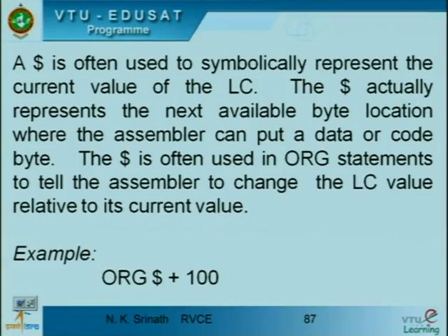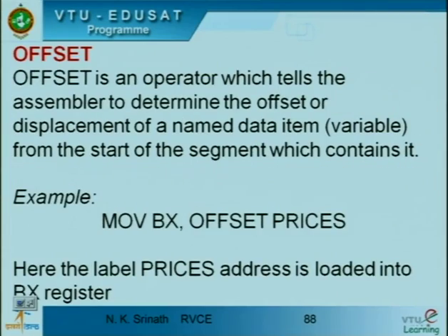It so happens that when you want some space to be left aside and the data to be stored later, you use this statement called ORG dollar plus 100. It means that whatever is the point where you start, that is mentioned as dollar, and from that point leave 100 locations and later start storing the data. That is what this particular statement does.